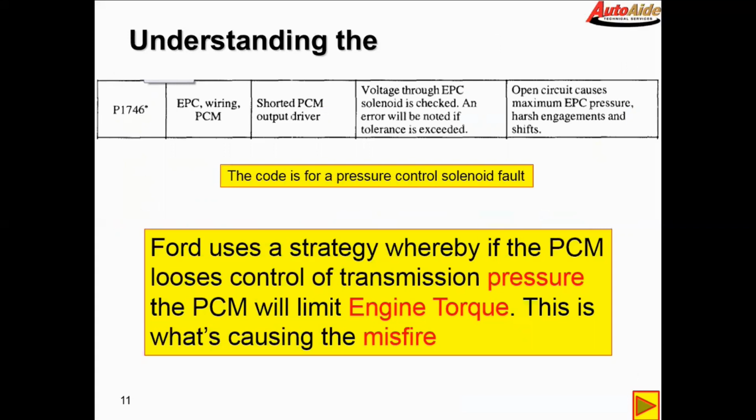That has gotten better as we get into newer and newer trouble codes, and generally on modern cars, especially drive-by-wire cars, if the computer is throttling the engine back for whatever reason, there will usually be some kind of code in the engine controller indicating that torque is being managed and to not chase the low power issue, chase the other thing.